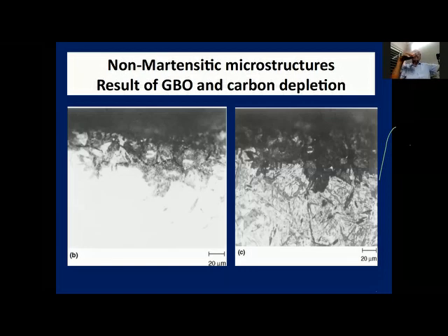And in some cases, the GBO as well as this kind of microstructure may be accepted for some components because they are doing either gear grinding or honing. Under those conditions, the design may permit some amount of these phases, but generally, since it is indicative of bad control, it is not recommended at all. Next, please.